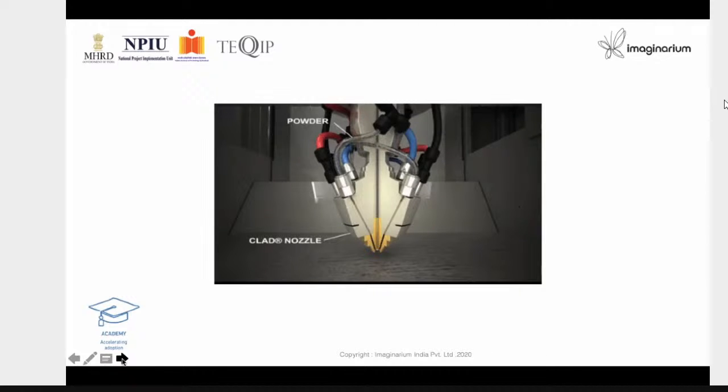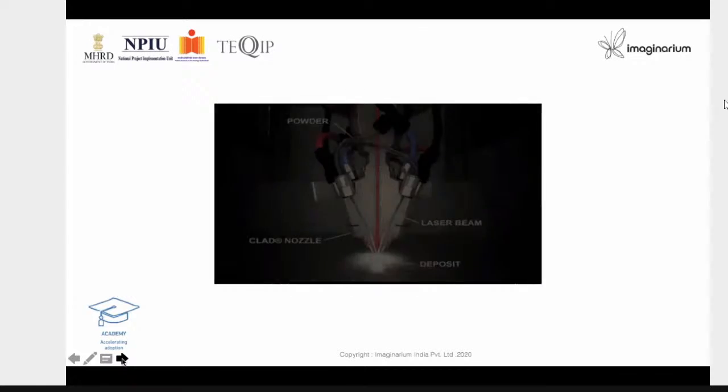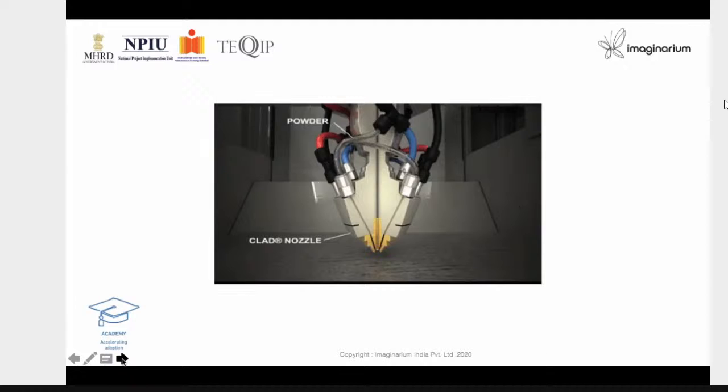What you see there, conical head receives metal powder on either side. And in the center, you have the laser coming. It could be a laser or a plasma or whatever. And as it comes down, the molten drop of metal is deposited on the substratum. Okay, that's what happens. And with this continuously pouring in sync, we are able to deposit and make objects.